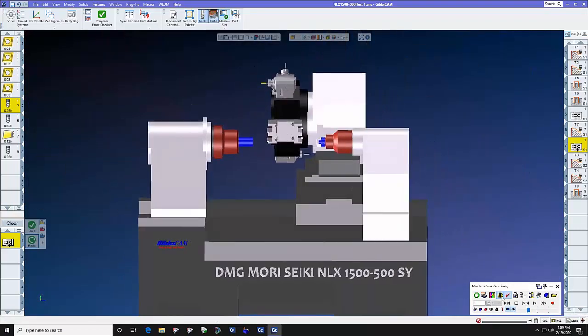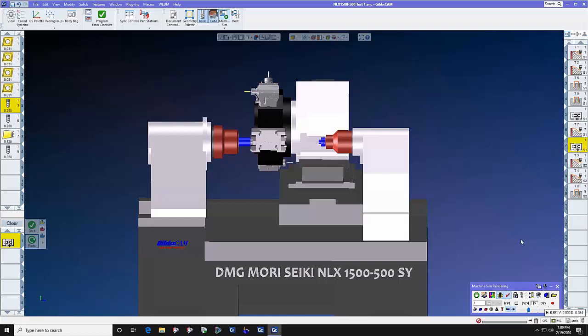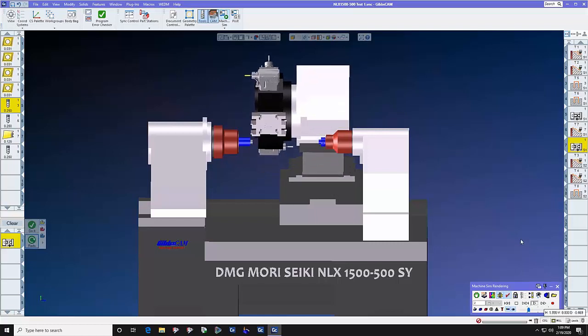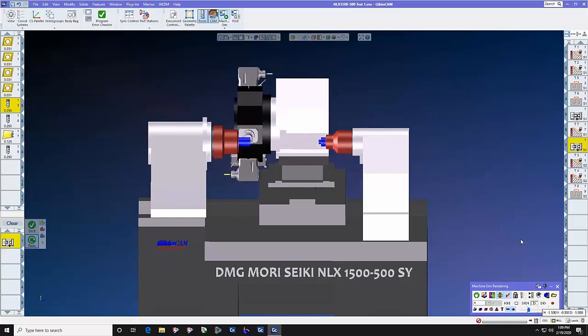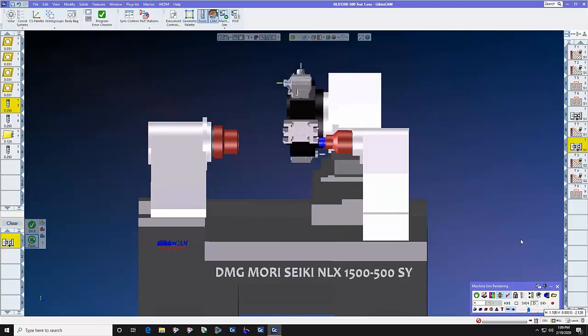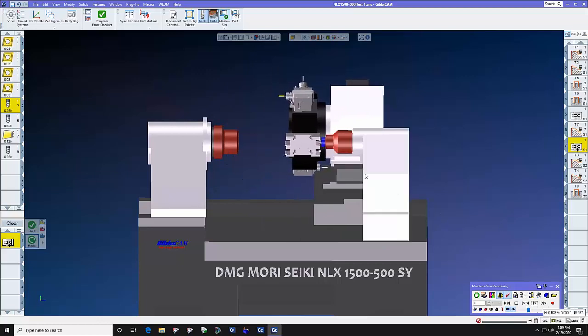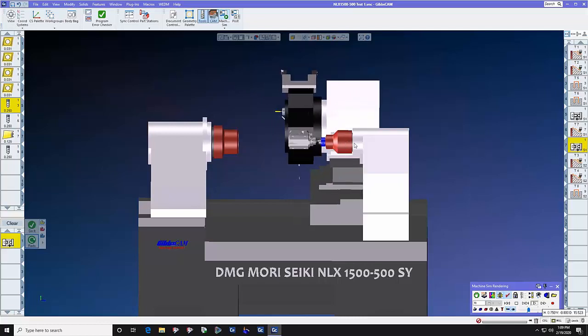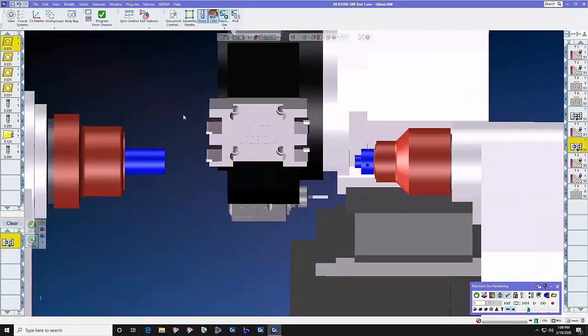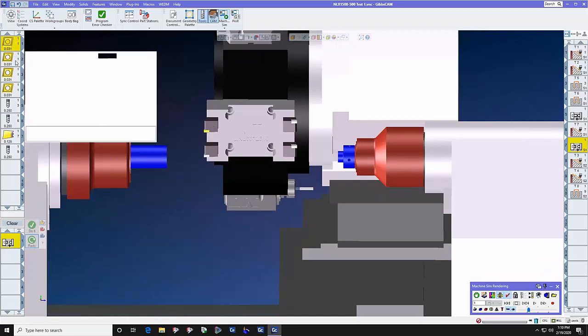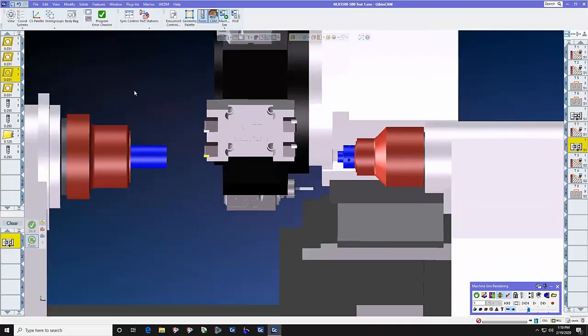Let's watch this part run one more time so that you can see all the things that we've covered, and you can also see that this quad tool holder is automatically commanded to move in the Y-axis by GibbsCAM because GibbsCAM understands where each of those 4 tool tips are. As soon as the part file is done running, I will show you how we identify the tooltip position. And here, we're going to go back to rewind, and the top of the program, if we click on tool 1 and force a redraw, tool 1 is highlighted in yellow, and so on.